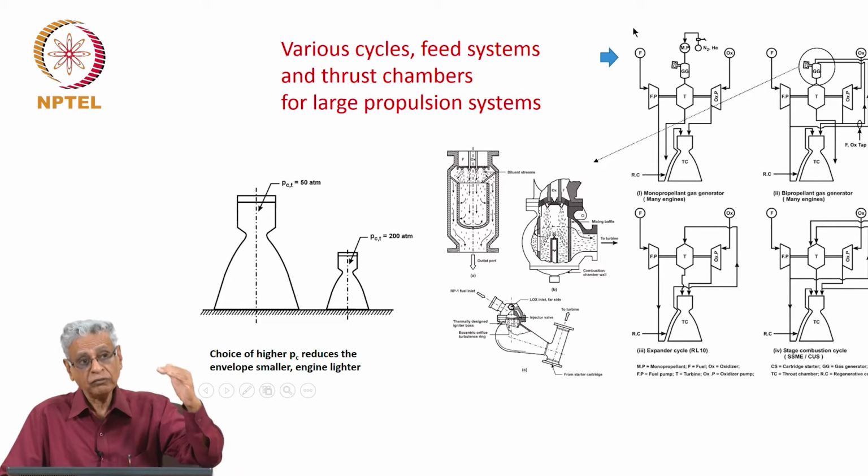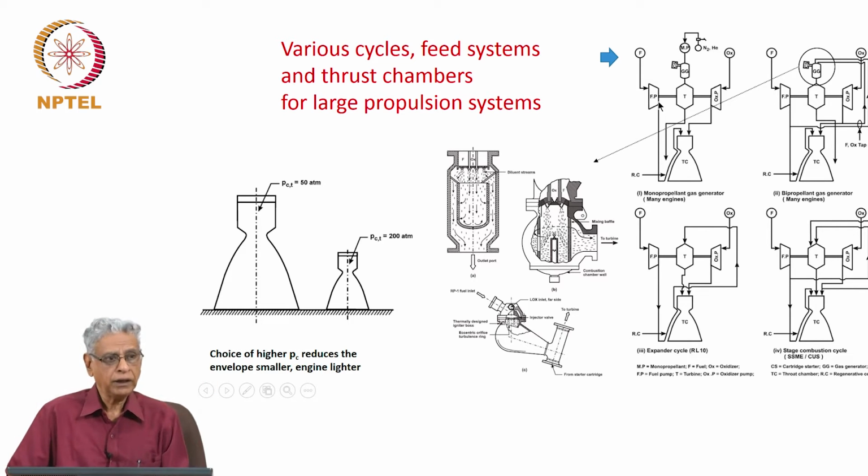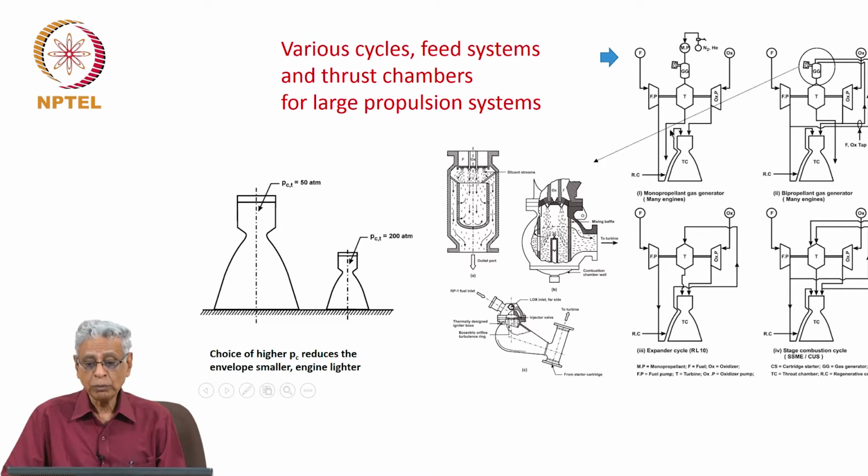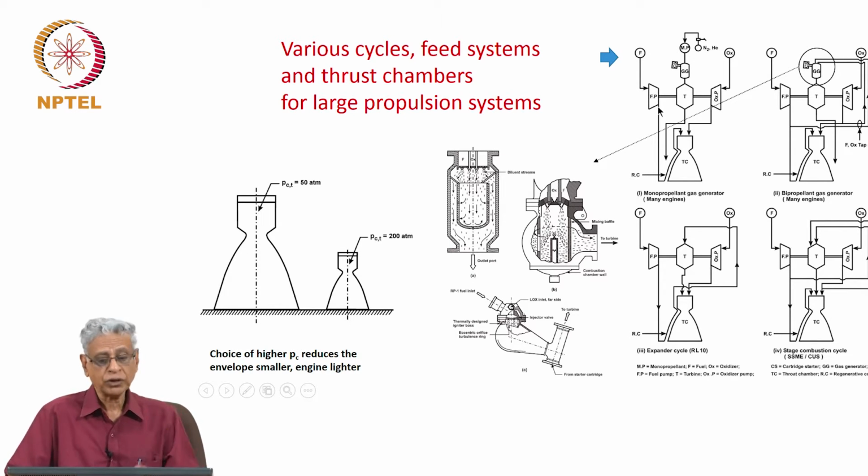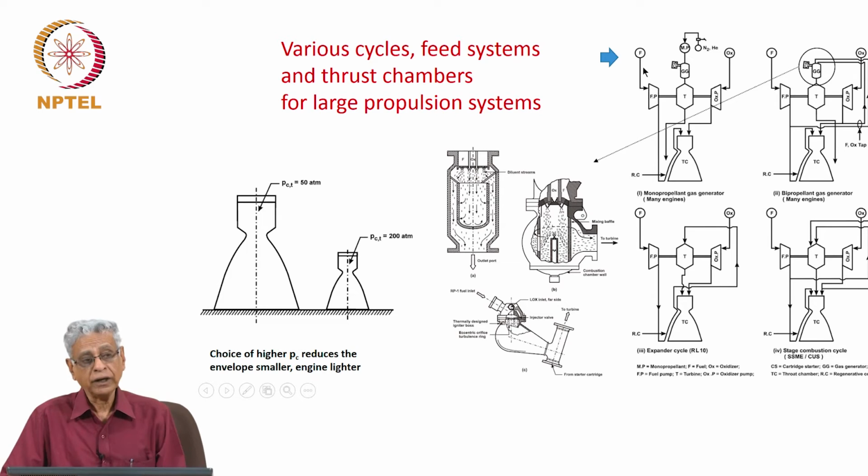That pressure will deliver the liquids into the pumps to ensure that when these are operating at high speed, no cavitation occurs, and these pumps deliver the fluids at pressures whatever is required here. And if you take a pressure here of 200 atmospheres, you will be looking at pressure at the turbo pump of 500 atmospheres. If you are looking at pressure here of say 300 atmospheres, you may be looking at 700 atmospheres as the pressure of the liquid after the turbo pumps. So, this really operates in very difficult conditions, if I may say so.